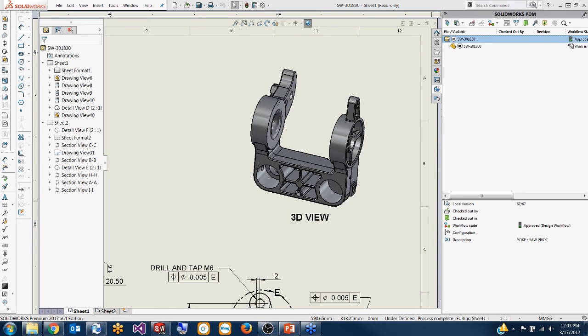So if you want to find something that takes your sheet metal parts, automatically flattens them and converts to DXF, PDM Pro won't support that out of the box. You'd have to do some kind of custom scripting for that. But if it's just a drawing, converting that to DXF, that we do support. Let's move on here.